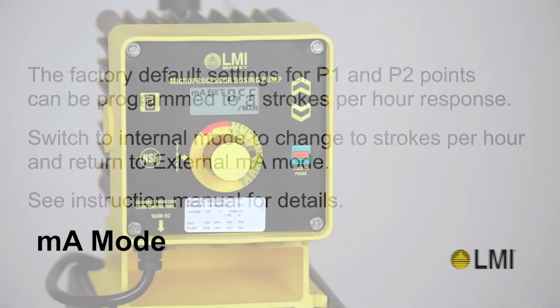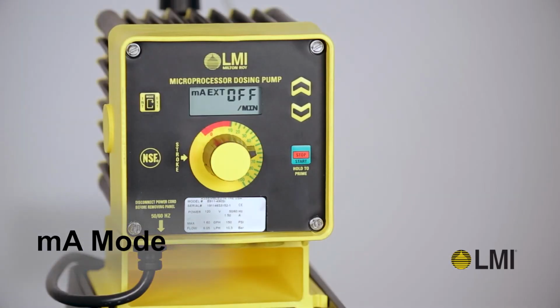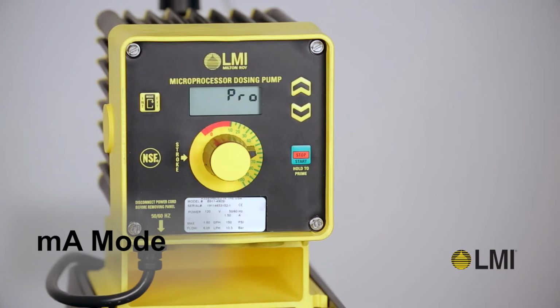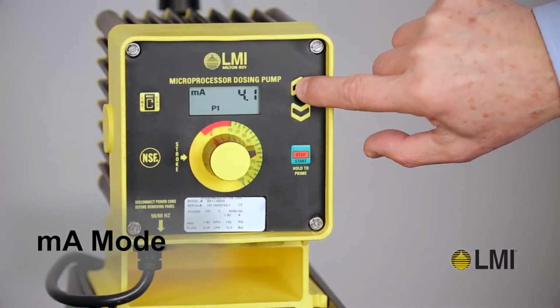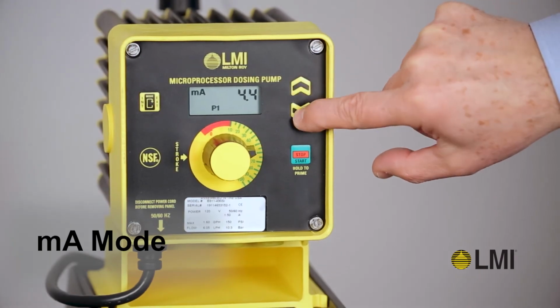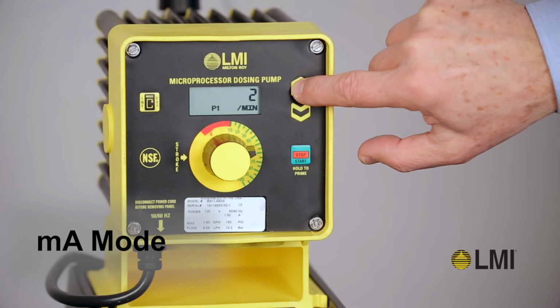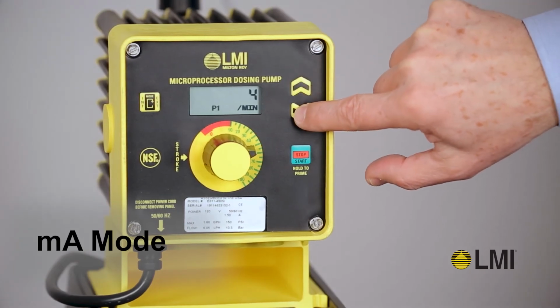When in milliamp mode, the pump speed and the milliamp value are displayed alternately every 4 seconds while the pump is running. To program the P1 and P2 points, press the up key to begin programming. Pro will be displayed on the screen. Input the milliamp value for P1 by using the up and down arrow control keys. After a brief pause, the strokes per minute for P1 will appear. Input the strokes per minute value for P1 by using the up and down arrow control keys.